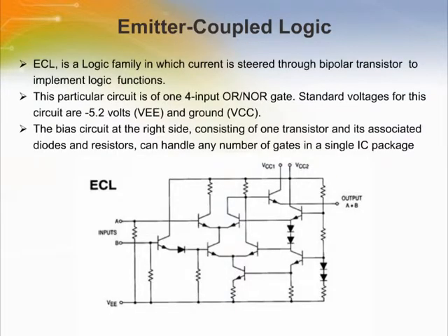ECL, also known as emitter-coupled logic, derives its name from the differential amplifier configuration, in which one side of the differential amplifier consists of multiple input bipolar transistors with their emitters tied together. An input bias on the opposite side of the differential amplifier causes the amplifier to operate continuously in the active mode.